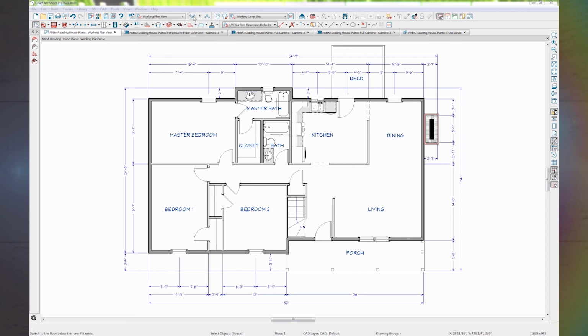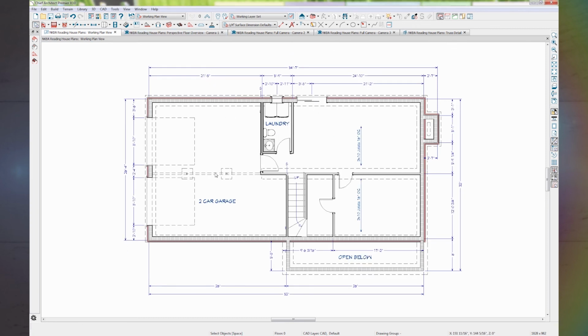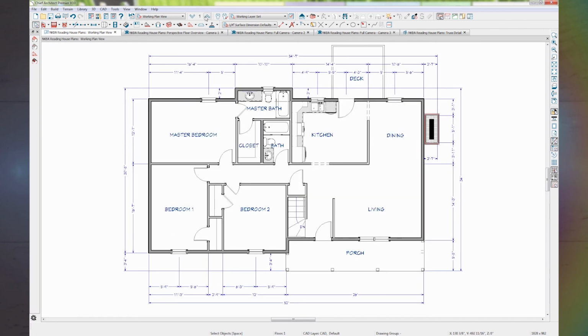I have a few clues. In the basement, the garage beam and the structural wall were centered in the space. This means any load-bearing walls should be directly above the basement beam and wall. Also, load-bearing walls that are supporting the roof load would need to continue the entire length of the house. Neither of these walls are that long. While it is possible to have beams replacing walls, as we've seen in the basement, no beams are indicated in this plan. When I turn on my reference so we can see the walls below, notice that neither wall is directly over the load-bearing wall in the basement.